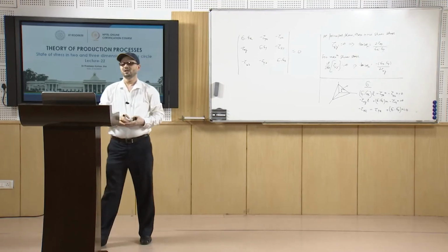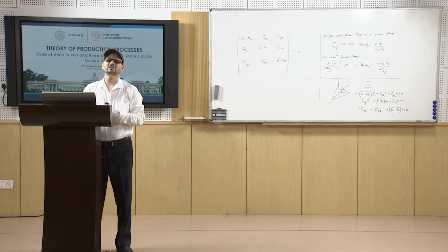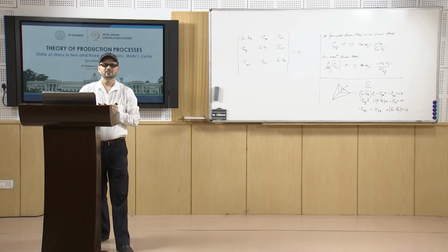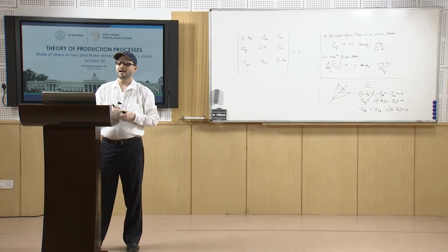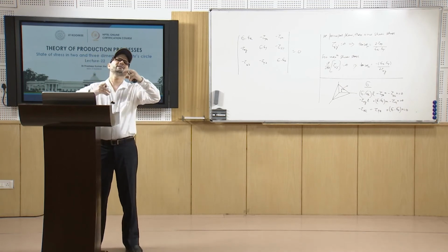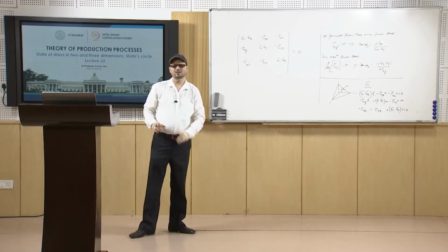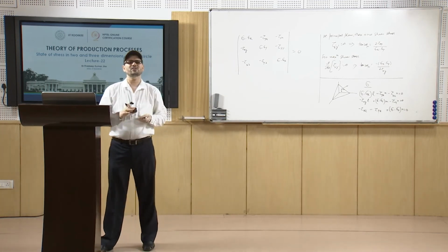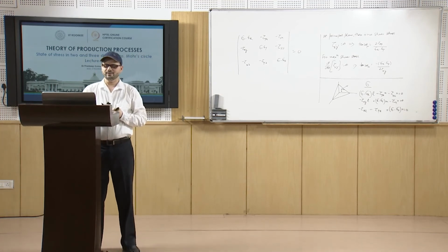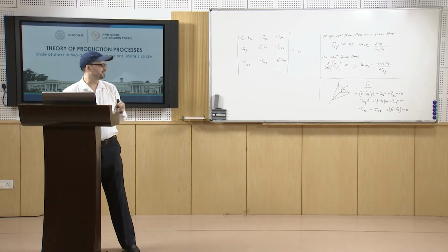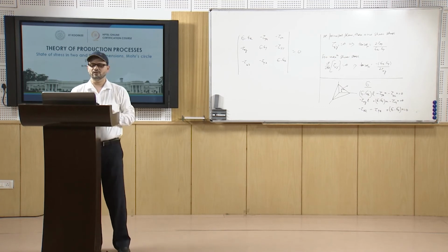Once you equate that to 0, you get 3 roots, sigma 1, sigma 2 and sigma 3. So, there will be 3 principal stresses acting, and that gives you the solution.